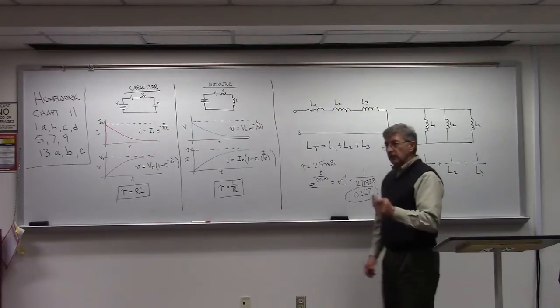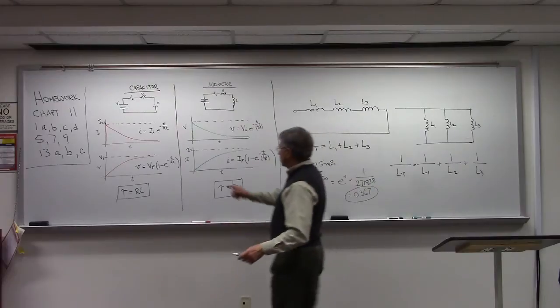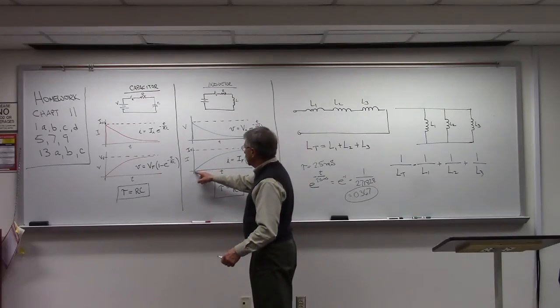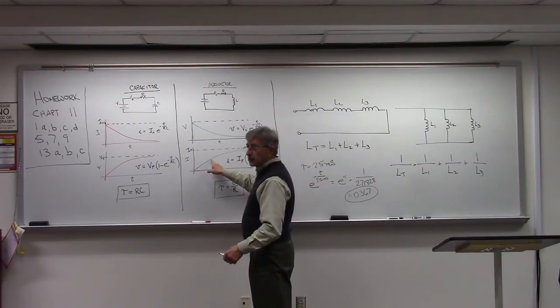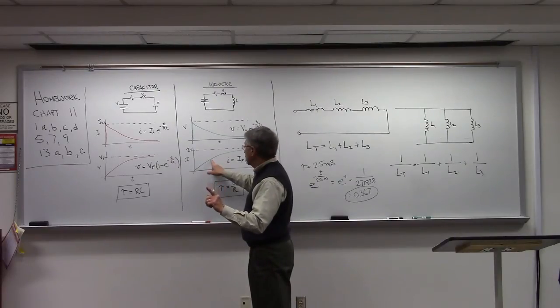So in 2.5 milliseconds, this curve has gone from nothing to about 37% of its maximum. All right? So that's one time constant.